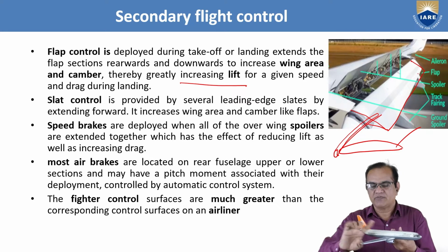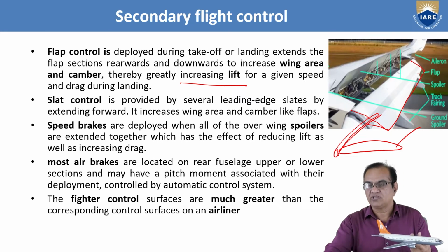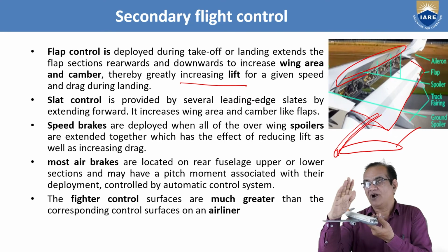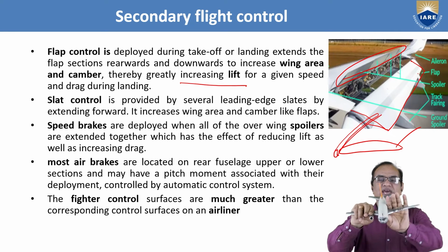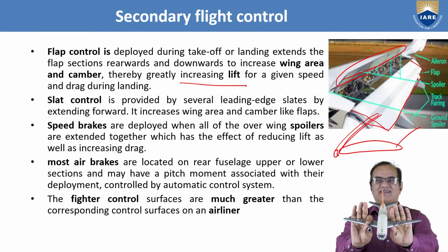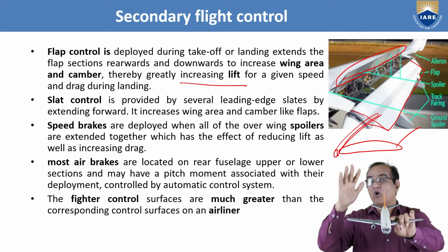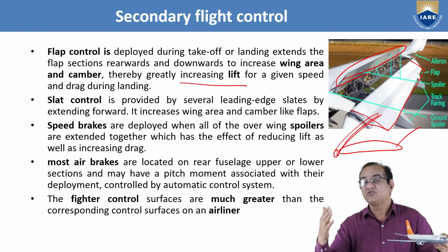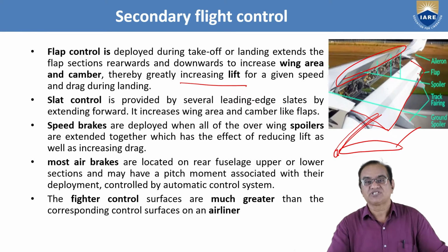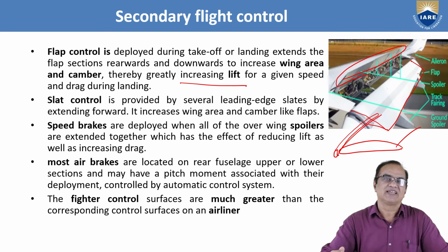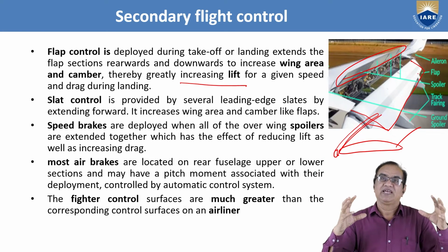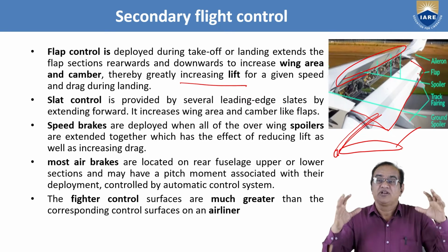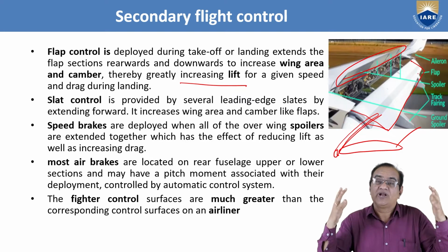At that time, these plates, which you can see here, are raised upward like this. Everywhere it will come like this, so the air will give more resistance and your aircraft speed will be reduced. But we cannot reduce the speed below the stall speed, otherwise the aircraft will start sinking. So we should make sure that the speed brakes or spoilers are used, and these reduce the lift and also increase the drag.